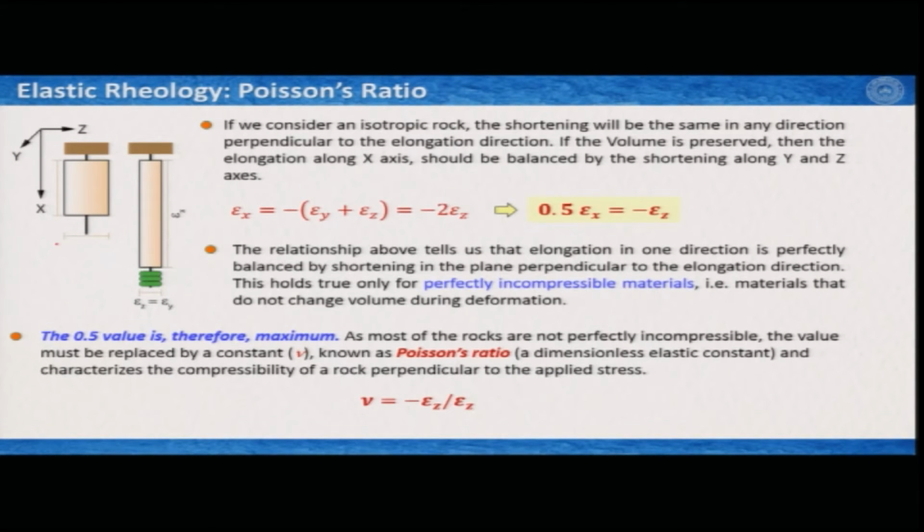So, this was initially the width of this bar, say this is a spring and this is the length of this spring. Now, upon applying this load, these green bars, then I can figure out the strain which is along x direction, which is epsilon x, and if I consider this is cylindrical and a perfectly isotropic body, then in this direction it has to shorten to keep the volume constant, and therefore, epsilon z and epsilon y should be equal.